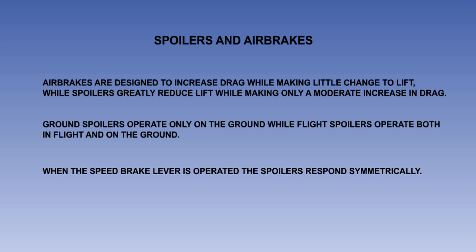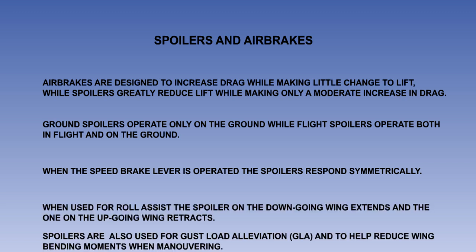Bear in mind that when the speed brake lever is operated, the spoilers respond symmetrically. But when used for roll assist, they operate asymmetrically, the spoiler on the downgoing wing extending and the one on the upgoing wing retracting.